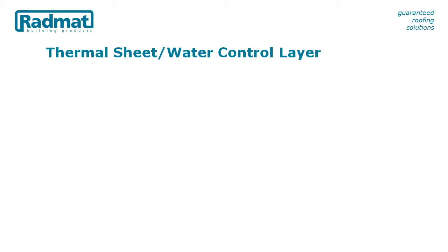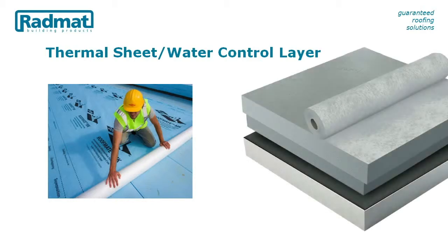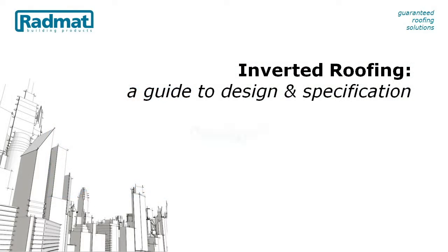The final key component in the evolution of inverted roof systems has been the addition of the thermal sheet or water control layer. This rolled material, typically manufactured from spun-bonded polyethylene, is loose-laid over the insulation board with 300 mm overlaps. It provides the means by which 90% plus of incident rainfall is drained from the roof. Key to effectiveness in use is the detailing, more of which later.